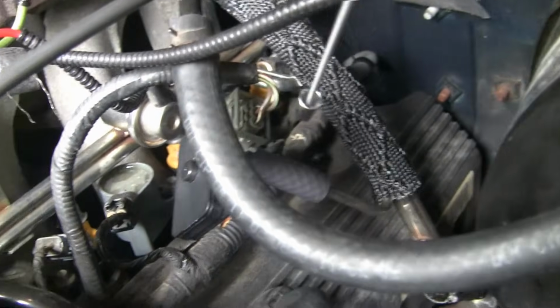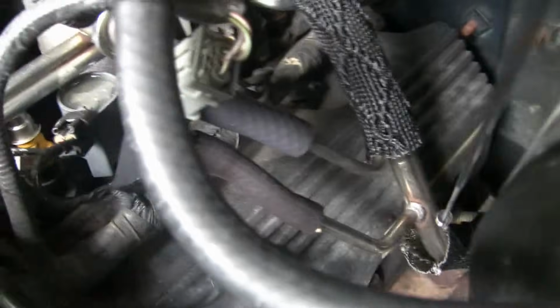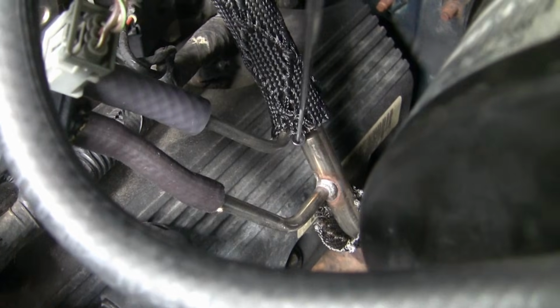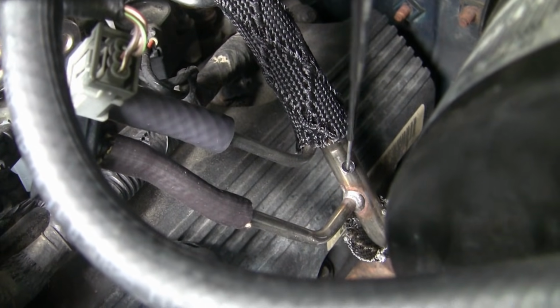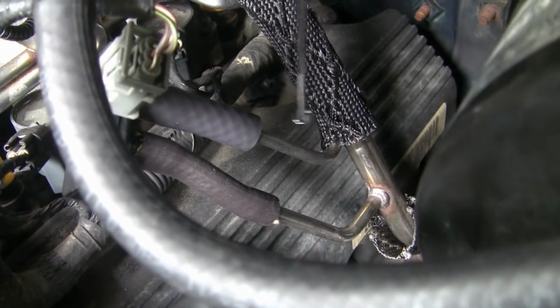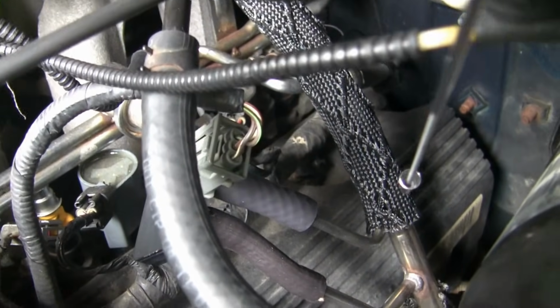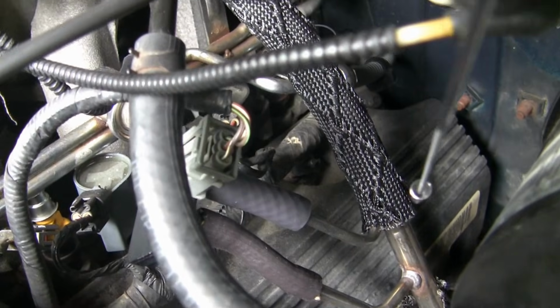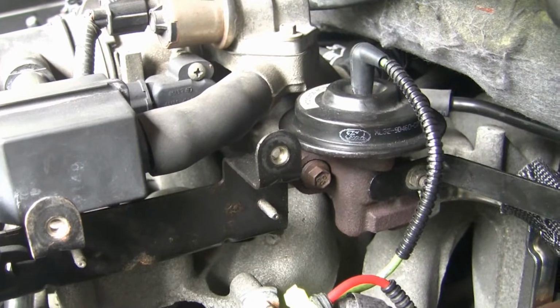Now, the DPFE sensor, as the name implies, it's a sensor, and what it does is it connects to the EGR tube down here, and in between here and here there's a little orifice in this pipe, and the sensor actually measures the difference in pressure between tube A and tube B and sends that data to the computer. And then the computer uses that data along with a lot of other data from the engine to determine when to turn the solenoid on to activate the EGR to let gas flow into your intake.